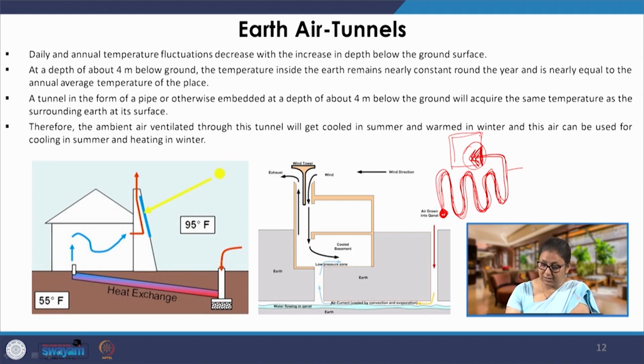There, what they have done is draw the air to the level where there is an underground stream, and they allow the air to pass over the stream and be cooled again evaporatively, and then they take the cooler air from the lowest story of the building, and one story of the building will also be submerged, underground. Now, this earth again is going to be at a constant average annual temperature, and so the walls of this entire space are going to remain extremely comfortable throughout the year, warmer in winters and cooler in summers.